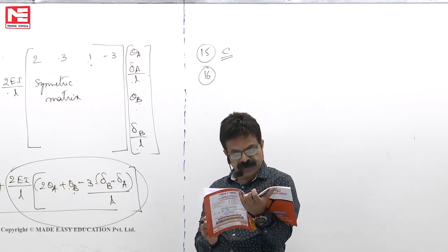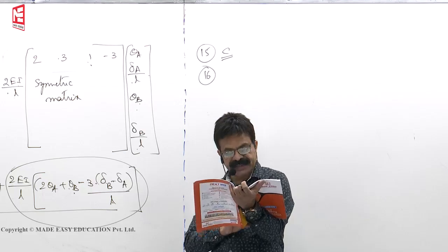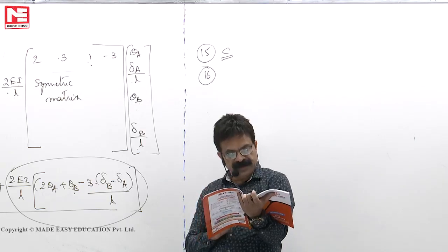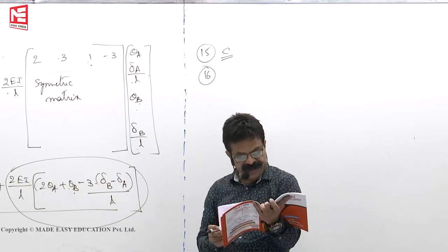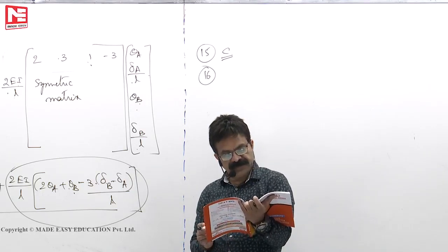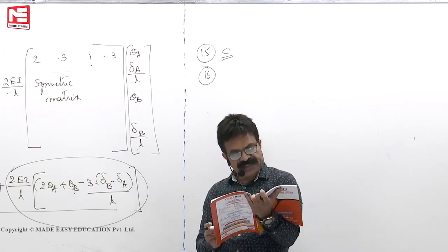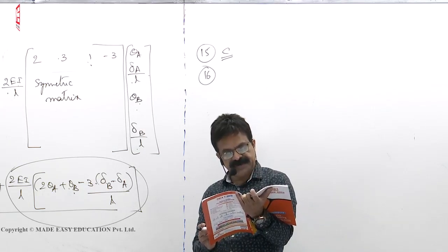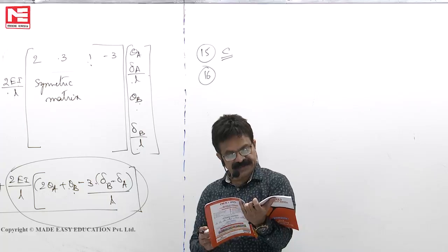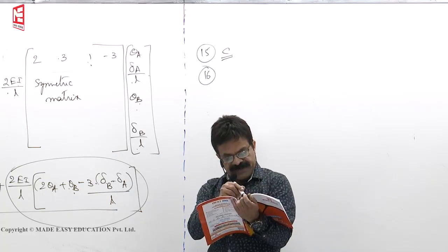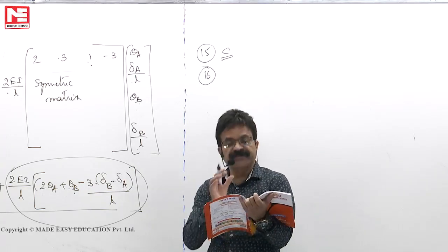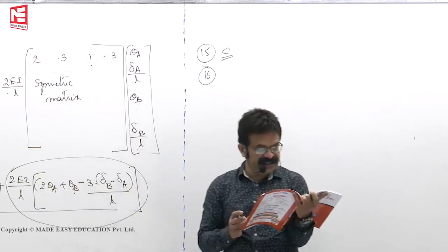Flexibility method is suitable for structures with smaller degree of statical indeterminacy than kinematic indeterminacy. Flexibility matrix is suitable for structures with smaller ds than dk. So D is correct. Flexibility method chooses the redundant reactions while stiffness method considers nodal displacements as basic unknowns. 1 and D are correct. Now, the fundamental difference: he is asking the fundamental difference, not the characteristic.